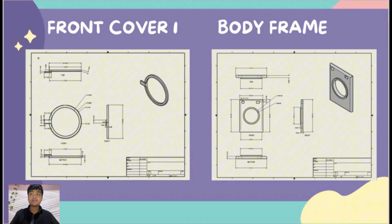The base from the front view is equal to 91.41 for the top, and for the bottom is equal to 91.38 millimeters, and the extrude value is equal to 5 millimeters.